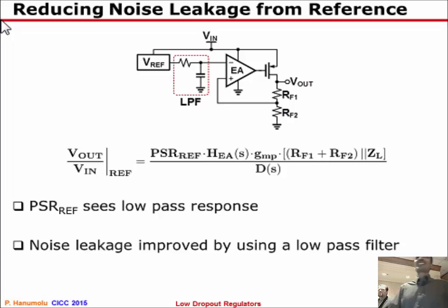For PLLs, I'm not entirely sure if the noise from this stage is going to impact, but regardless, the flicker noise from this stage can be made small simply by increasing the size.